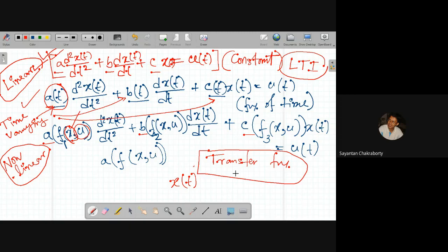So, okay, you have a basic idea of transfer function. In the consequent time, we will be developing an in-depth analysis of transfer function, that is the application of transfer function, why the transfer function is necessary, and what are the limitations of transfer function, and how the transfer function limitations can be overcome. So the first and foremost limitation of transfer function is that it is only applicable when the initial conditions are 0, and it is only applicable for linear systems, right?